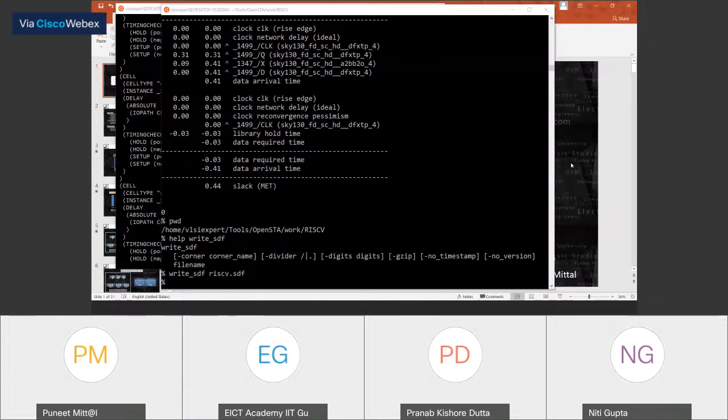The tool will never come to know that particular part. So that means .lib is required for the linking purpose. But inside the .lib, where we are talking about the matrices, the timing information, the timing arc, if we are saying that I'm going to change those values, what is happening? The tool is doing the calculation every time.